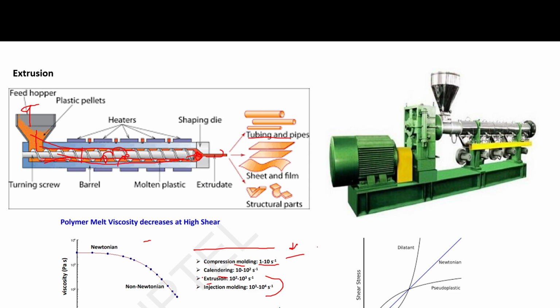Regarding the difference between extrusion and injection molding, extrusion molding is generally used for large types of products like tubing, or with extrusion blow molding you can make products like bottles. But injection molding has a more intricate design, so if you need a small product with various designs, you can make it by injection molding. It is a more complicated instrument as compared to extrusion blow molding.